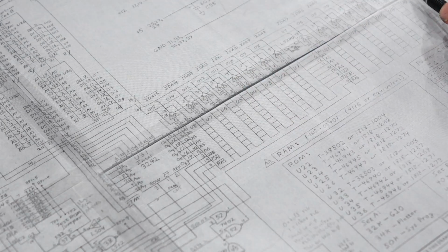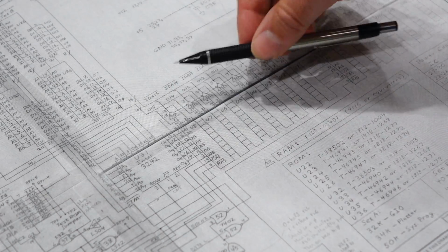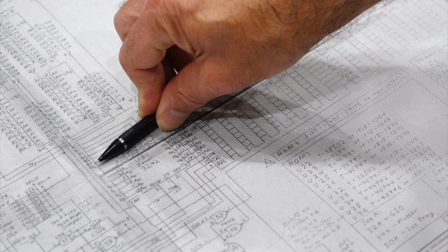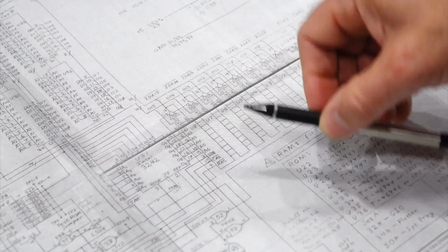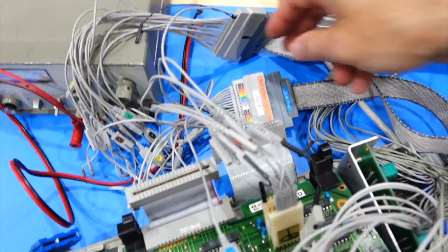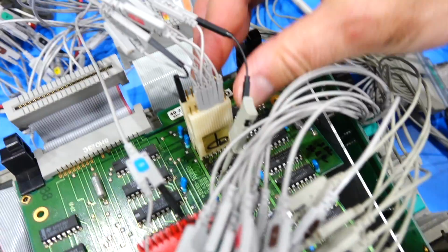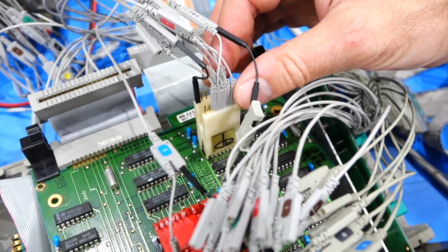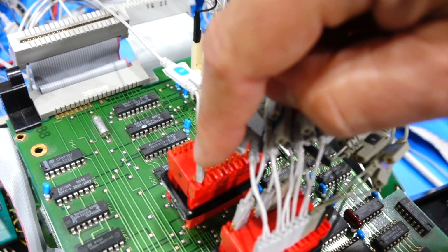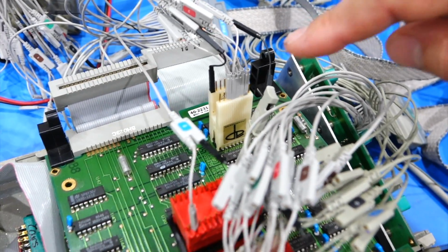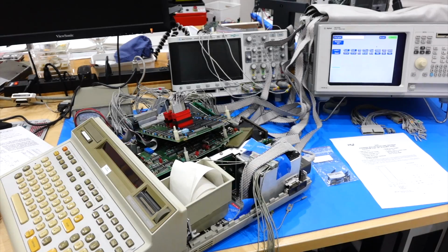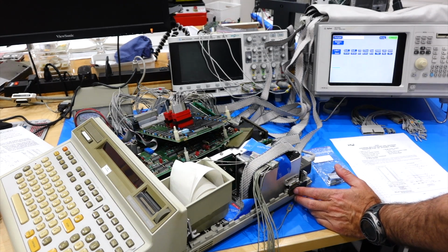So a couple episodes ago, we already knew we had an either-or situation, and we only went after the refresh noodle logic, mostly because of the logic analyzer traces. But the simulation is now telling us that we should probably question our Intel controller instead. I have added a few pods to the configuration, so now pod 6 is testing the RAM and the 6 bits of address. And also it has a line on the Intel chip for the refresh signal. So the idea is to try to catch a refresh cycle and see if the address counts. So it's a very basic setup. So off we go, trying to capture refresh cycles.